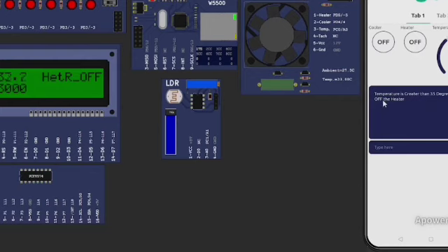Now, if I talk about the cooler, when I press this cooler button, the fan is rotating now, as we can see, and the temperature is decreasing. The cutoff for temperature is 27.9 degrees Celsius. At that temperature, the cooler should turn off and a notification should appear here. As we can see, the notification also appeared here saying that the cooler has turned off because it is a normal room temperature. This is about our temperature sensor project. That is the second part of our project.